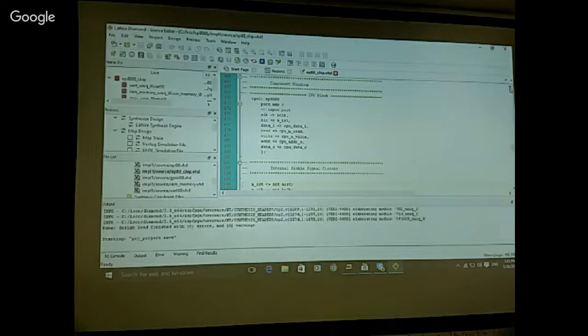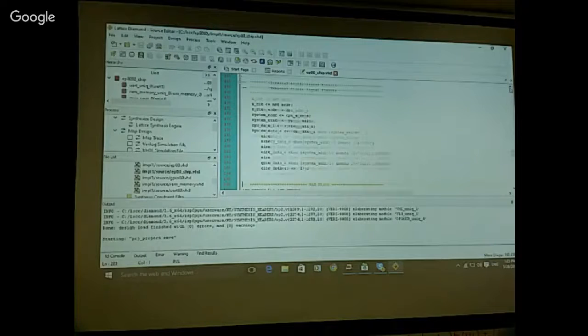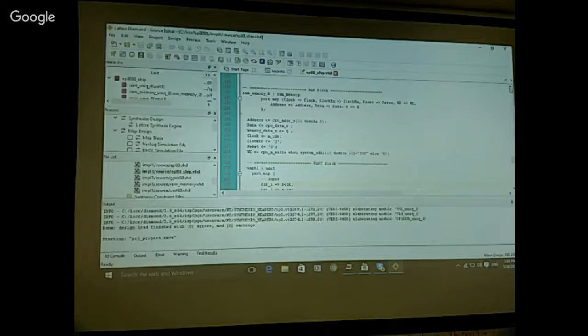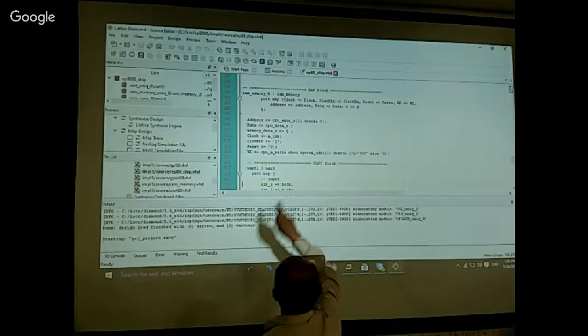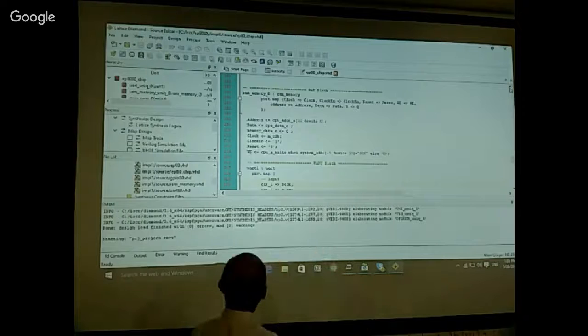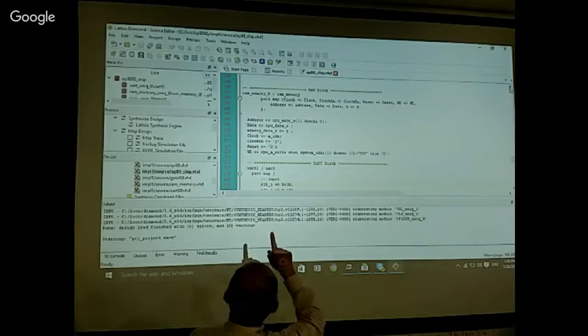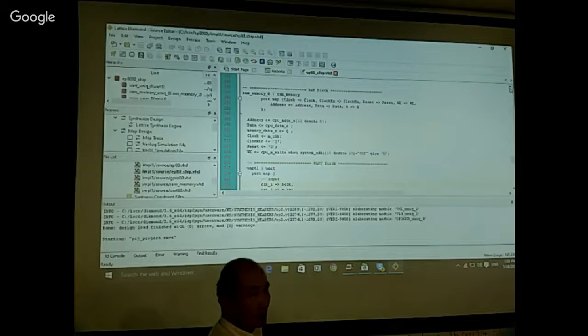And so here is the memory module. It shows that its input has the address. Where does the address come from? It is generated by the CPU on the bus CPU_ADDR_O, and that's a 13-bit bus.